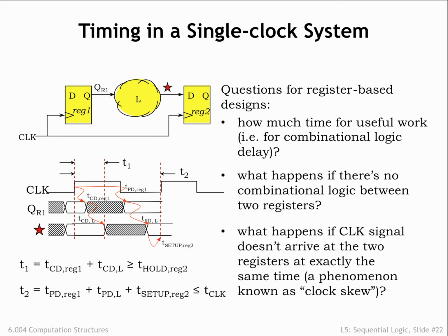You may have noticed that Intel is willing to sell you processor chips that run at different clock frequencies. For example, a 1.7 GHz processor versus a 2 GHz processor. Did you ever wonder how those chips are different? As it turns out, they're not. What's going on is that variations in the manufacturing process means that some chips have better TPDs than others. On fast chips, a smaller TPD for the logic means that they can have a smaller T-clock and hence a higher clock frequency. So Intel manufactures many copies of the same chip, measures their TPDs, and selects the fast ones to sell as higher performance parts. That's what it takes to make money in the chip biz.